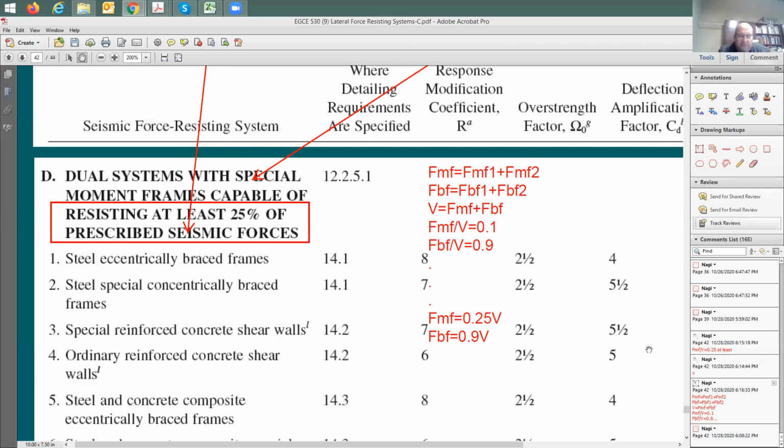This is going to be beside all of this discussion. At the end, we're going to have this eccentricity, and we have eccentricity in the applied force, and we have eccentricity due to natural causes, because the location of the center of gravity might not be in the center of rigidity. And then also you have this accidental eccentricity, right? Which is 5% of the total length, which is not covered here in this discussion. But thank you very much for raising this issue here.